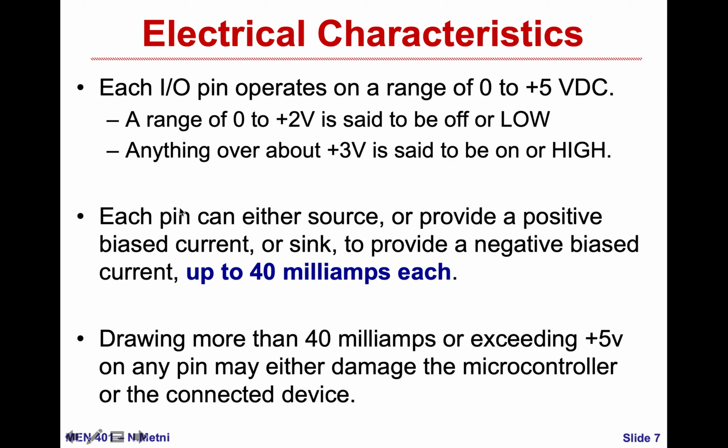But this is very important: each pin can either source or sink. What I mean by source is positive current, sink is negative current. So it can either source or sink up to 40 milliamp each. So never connect this directly to an LED maybe, or directly to a motor. Do not exceed 40 milliamp, or the damage will be large to the microcontroller and to the pin, or even to the device that you are using.